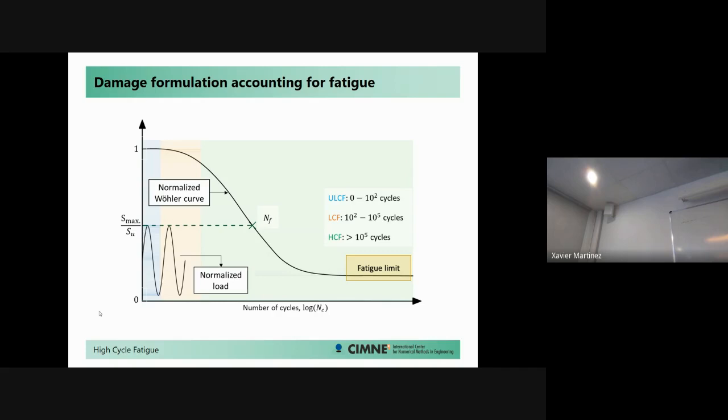For instance, at one of the most stressed points inside your model, you will be observing an evolution such as this. Actually, you have this curve available at any point inside your model. Any finite element, any integration point of that finite element has this curve available. But for us, the most interesting point, of course, is the one that is the most stressed inside the geometry, right? So what we are doing here, we are applying this active loading, okay? We have this maximum level of the load during one cycle.